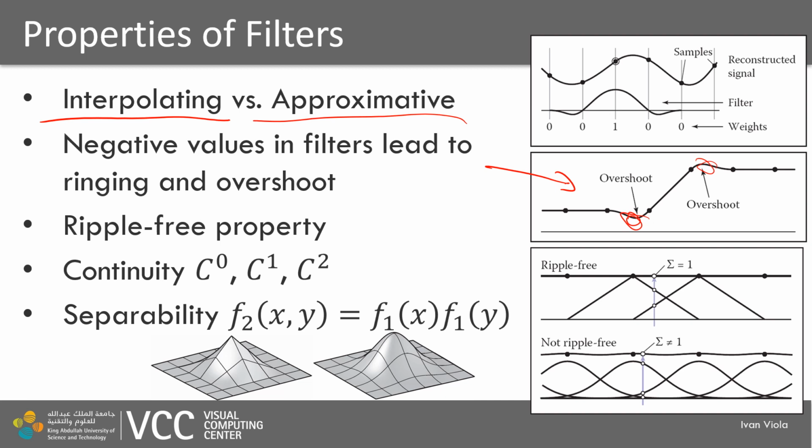We can also use, for example, the tent filter, and there will be no overshooting or undershooting, but there will then be a discontinuity between the sample points in the first order derivative, which will be visible and will appear in some flat sense as a result of such a reconstruction.